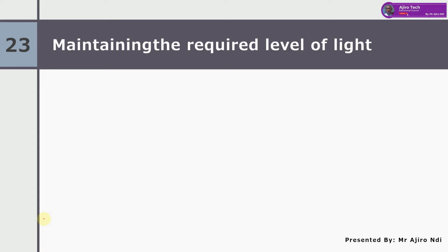Now, a second preset value therefore needs to be entered so that when the amount of light falls below that value, as at night, the light source is switched off. The steps required in this process are similar to what we have done in the two slides, except that two preset values need to be inputted. A light sensor is needed to measure the amount of light coming into the greenhouse, and the analog to digital converter is still required.